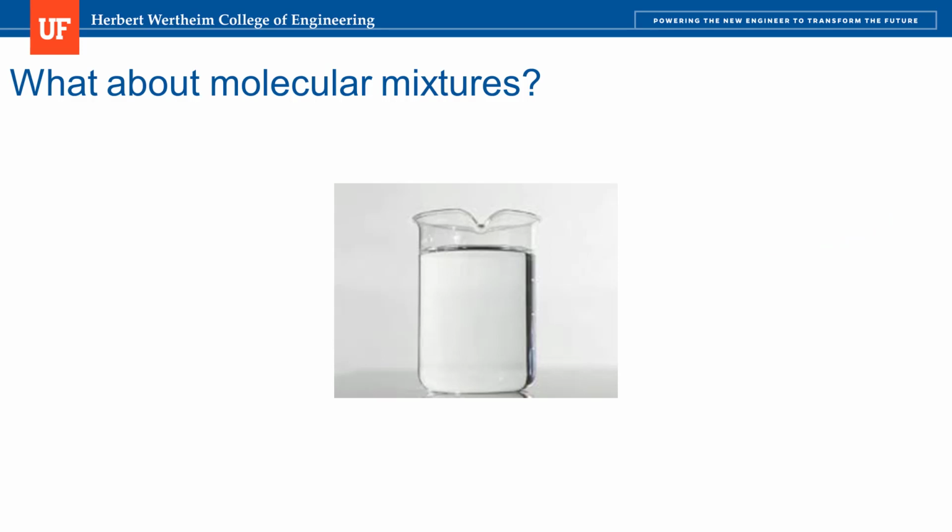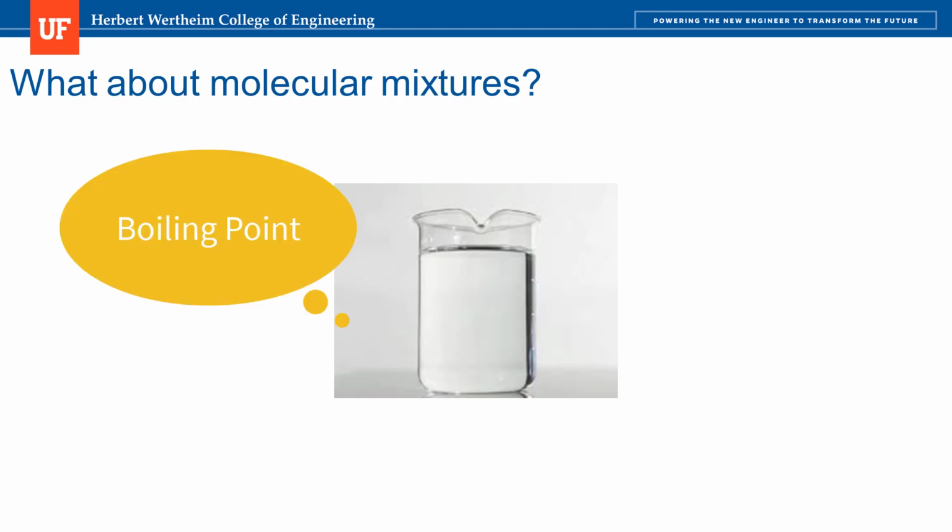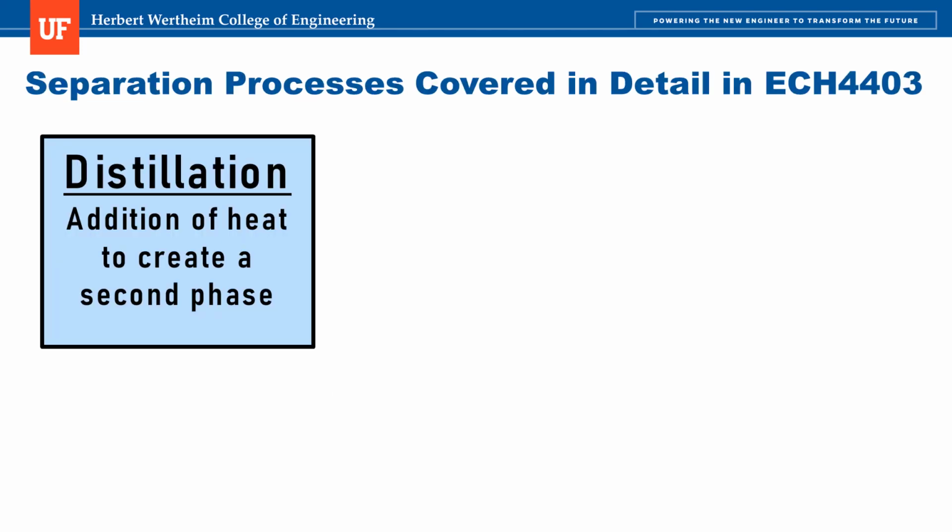What other differences can you think of that exist between water and ethanol that are exploitable? Any two given chemicals are likely to have a difference in boiling point, and this is an exploitable difference by heating or cooling the mixture to a temperature that is between the boiling points. In theory, the chemical with the higher boiling point should remain a liquid, and the one with the lower boiling point should vaporize. However, we know from phase equilibria that the separation is not quite that clean. There are laws of thermodynamics that we must obey.